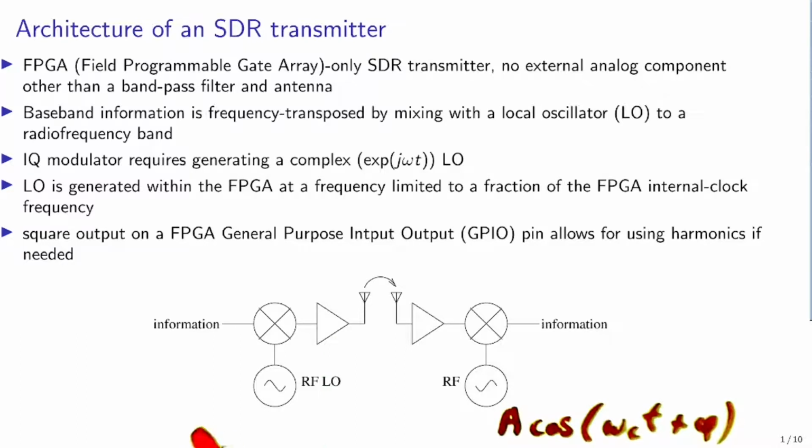This means that we will need in the FPGA to generate the information and this radio frequency carrier. This will be several megahertz bandwidth, and several tens to 100 megahertz carrier sine wave with its modulation scheme. Generating this multi-megahertz bandwidth and tens to 100 megahertz carrier is well beyond the capability of a general purpose central processing unit (CPU). Hence the need to understand and master the details of field programmable gate arrays, a matrix of reconfigurable logic gates that will be able to handle all these tasks of modulating information over a radio frequency carrier.